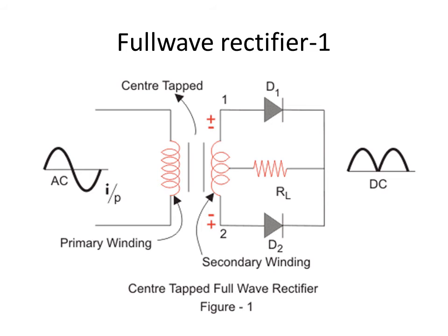And to find out the direction of current through RL, you start from the positive of the source. Bottom of the winding is positive, so from there the current will begin to flow, and it flows through diode D2 along the direction marked by the arrow in the diode symbol, and it reaches the junction, and it cannot go through D1 since it is open, so it will go through RL and reach the center tap point and completes the cycle.